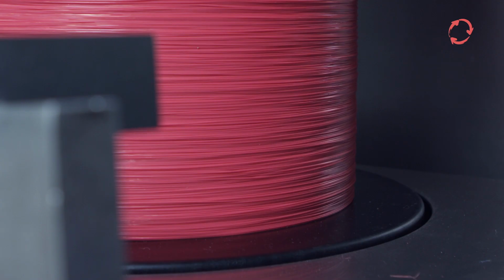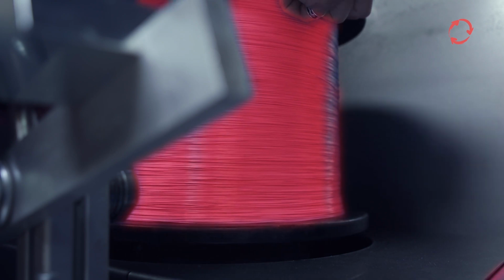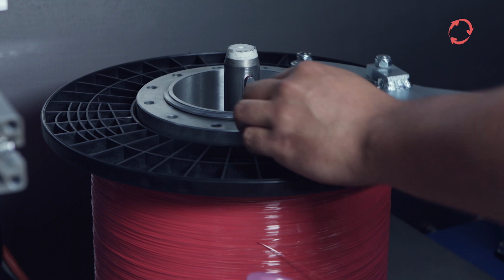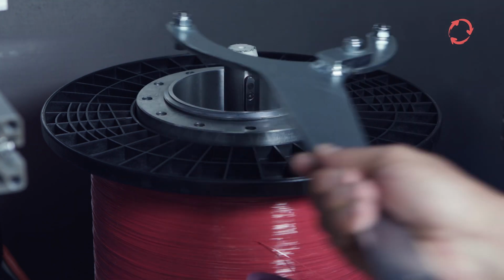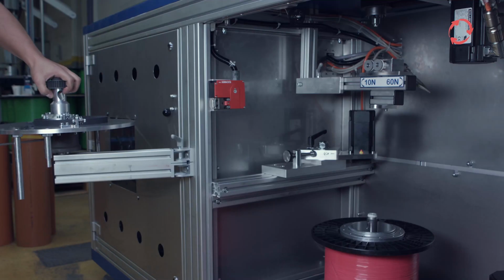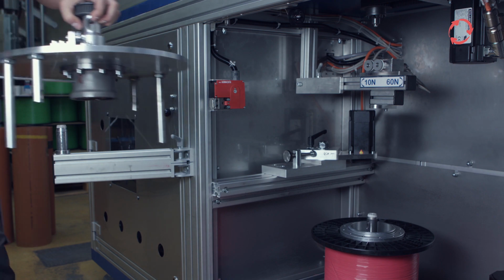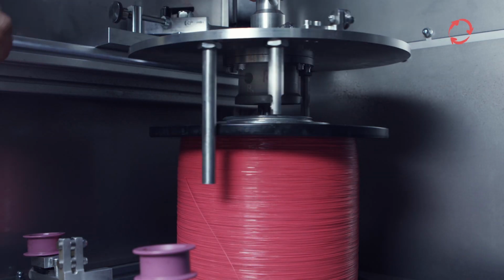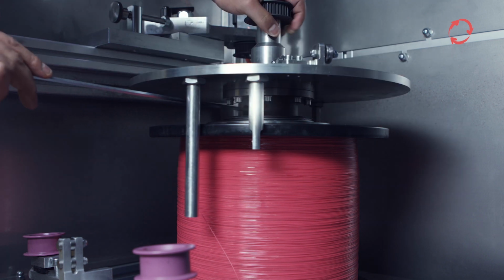When inserting the spool, it is very important that it sits on the spindle as far as it will go. If this is not the case, the coil can loosen during the winding process, and thread breakage occurs. Tighten the clamping disc firmly with a hook spanner. Take the winding plate from the depositing arm and put it back on the spindle. Make sure that the screw is tightened again.